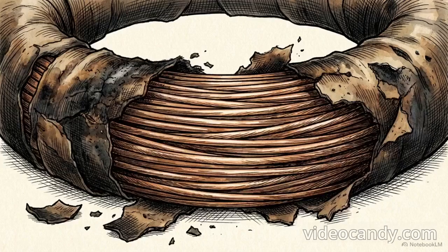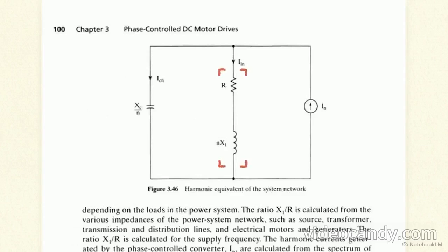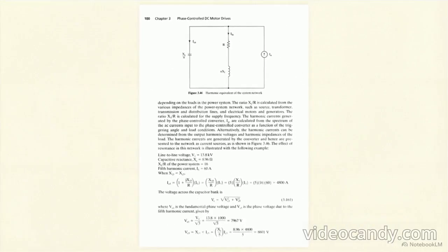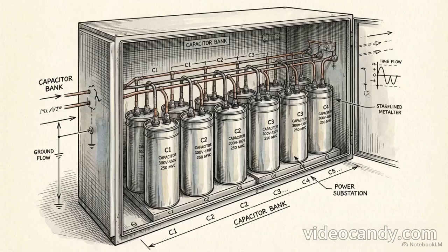Inside a distribution transformer, this excess heat bakes the insulation surrounding the copper windings. Under chronic high-frequency thermal stress, that insulation degrades, guaranteeing premature failure of the hardware. Furthermore, as these harmonic currents flow back through the system's inherent impedance, they create unwanted voltage drops. This deforms the actual supply voltage waveform, pushing instability onto every other piece of equipment connected to the local grid.